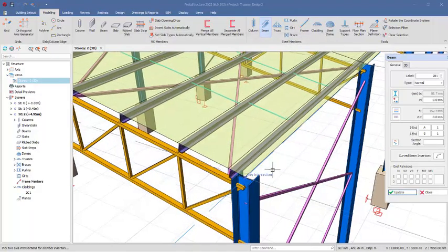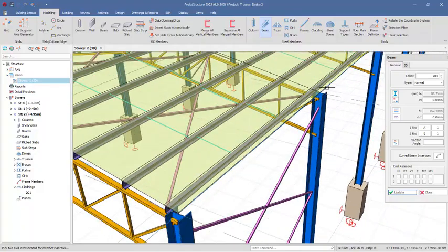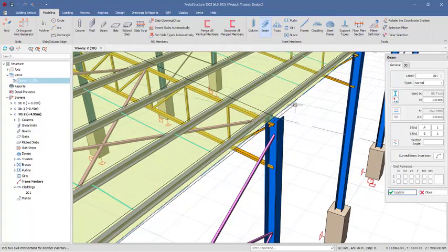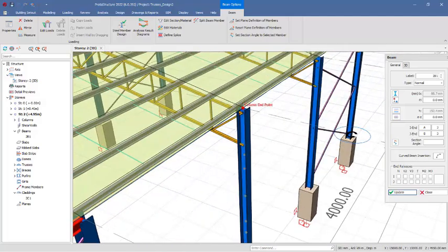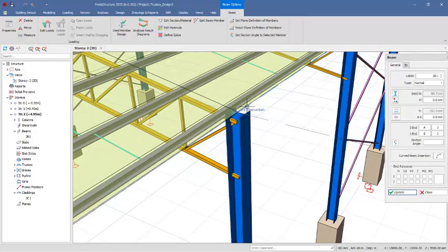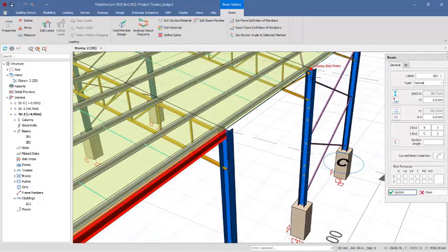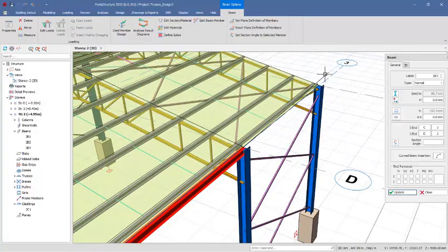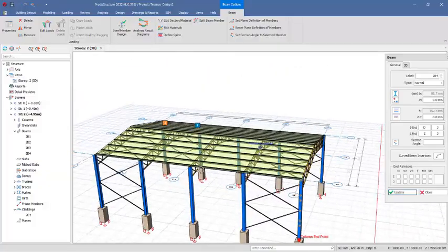So we will be taking it from one beam to another. All right, pick that and then take it to the next. So we'll be taking it from one column to another. So pick that first column, take it to the next one. Placing it like this is more accurate than placing it across. Okay, you may miss the node, and once you miss the node, you may not be able to have your structure connected in terms of connections. So you have to just calm down to ensure that you get the exact node point to place these beams successfully, just like this.